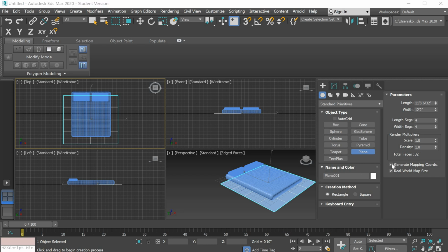Okay, so once you have that, go ahead and change the segments. We can make it really whatever you want it to be, just as many segments. The more segments you have, the smoother it'll be when it falls. So I'll try 30 for now.